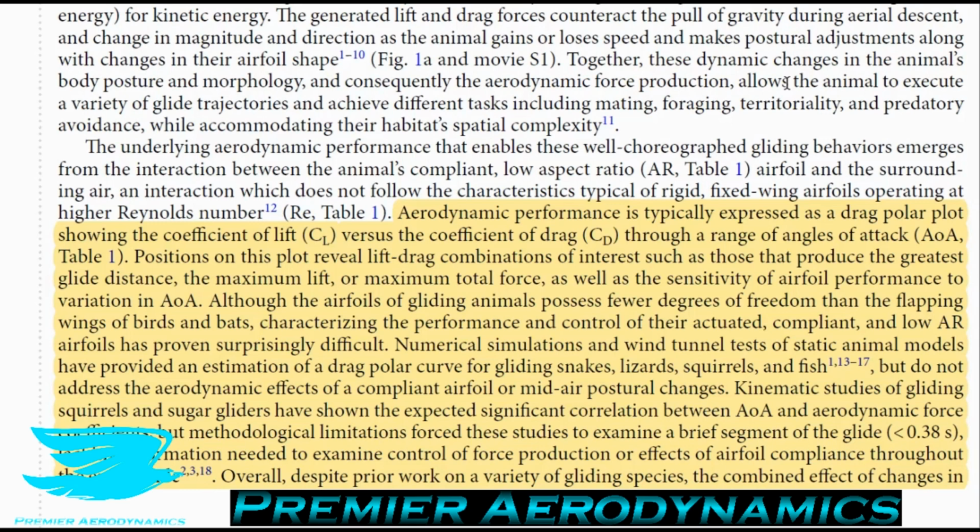And that means you produce less lift at the same angle of attack as a higher aspect ratio wing, but it means you can go to high angles without stall. So that's what aspect ratio is. I just wanted to cover that because it's a pretty cool concept that you don't hear too often.